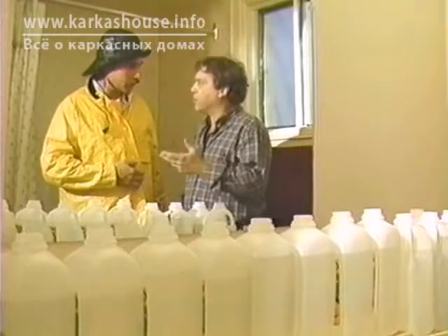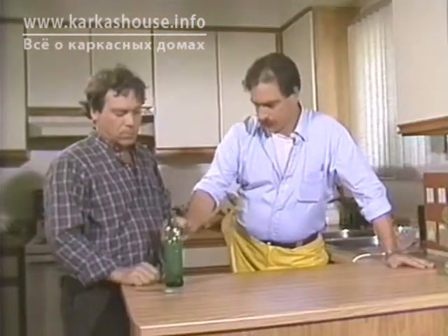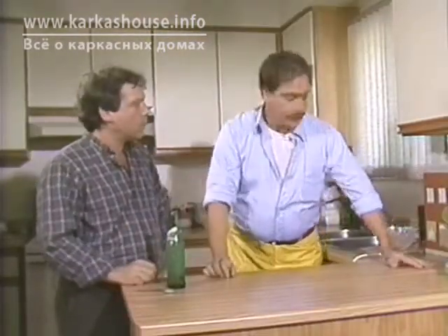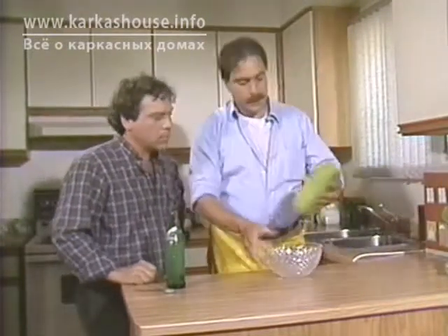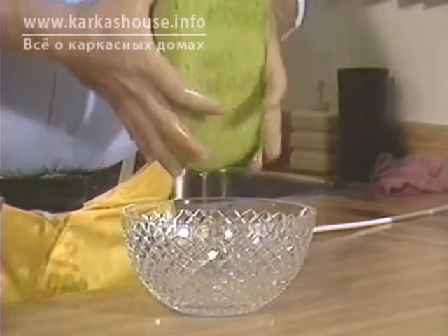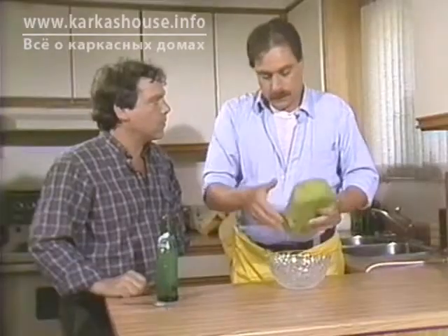So how does that water vapor turn into a liquid? Come on, I'll show you. I'm going to raid your fridge. We've seen a lot of sources of humidity. When that humidity becomes a problem for us is when it condenses on surfaces. And that occurs whenever the air that's carrying it is chilled. For example, on this bottle where it's starting to condense now. Now the reason that that takes place, if you would imagine this sponge as being the air, the ability of the sponge to carry water is reduced as the air gets colder and you drop that water out on the cold surface. Examples?